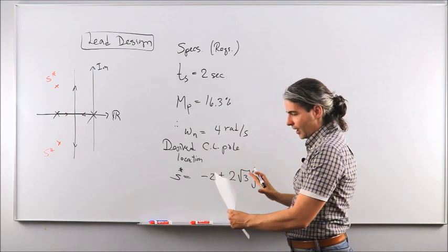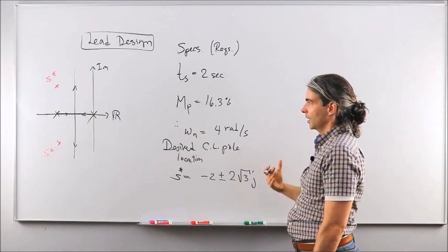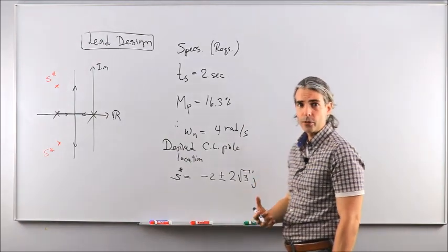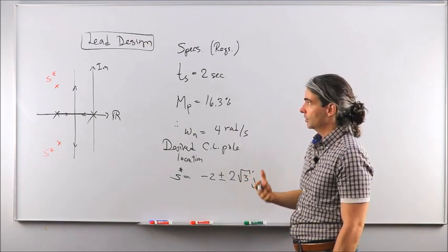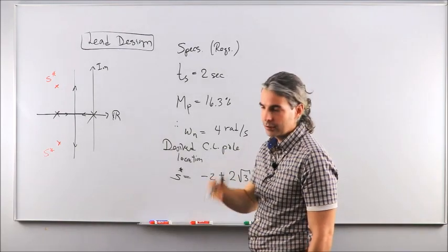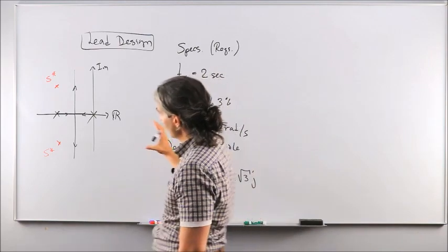Those are the specs I have. Those are the specs I need. And based on those two sets of performance, do I need to improve the transient performance or do I need to improve the steady state performance? And based on that discussion, then you pick the right compensator from your toolbox and design it and then apply it. Okay?